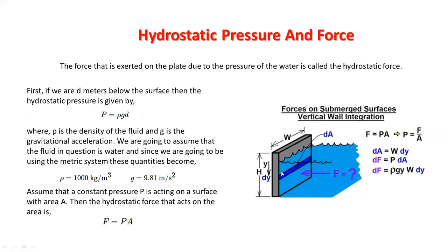However, as we go down, we will learn that pressure increases because the distance from the top of the plate going down increases. So while we say the pressure is increasing, we also say that the force is expected to increase as well, specifically the hydrostatic force. Why am I saying that when pressure is increasing as we go down, hydrostatic force is also increasing?